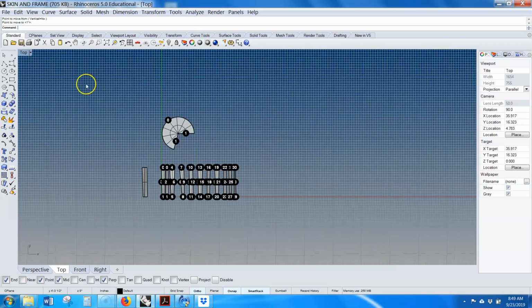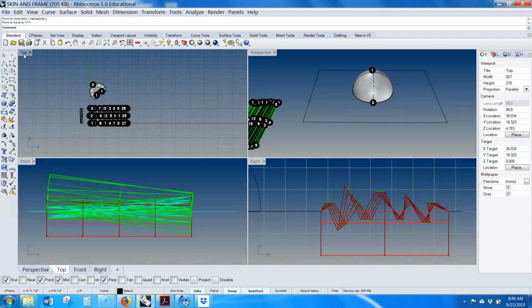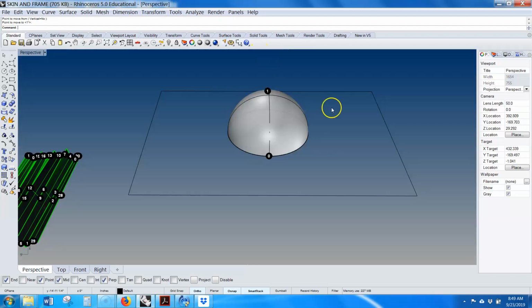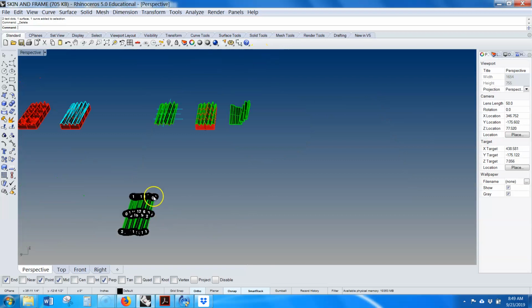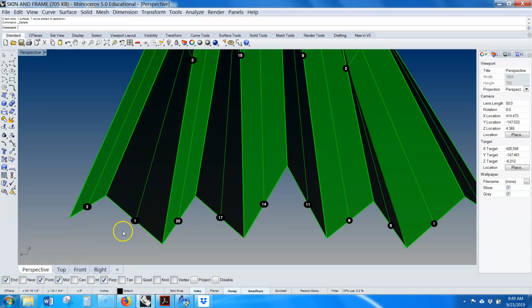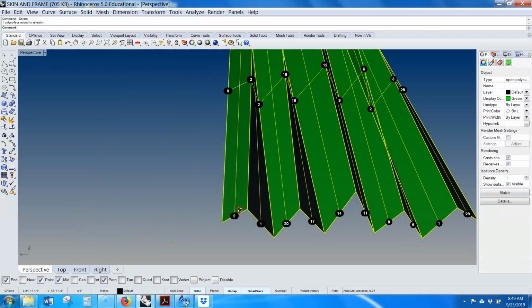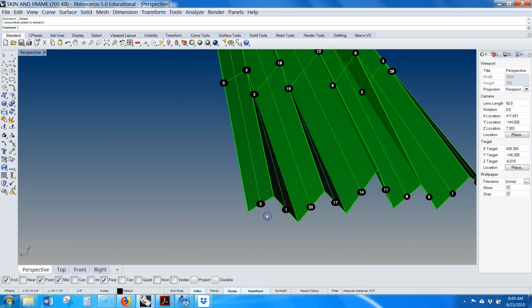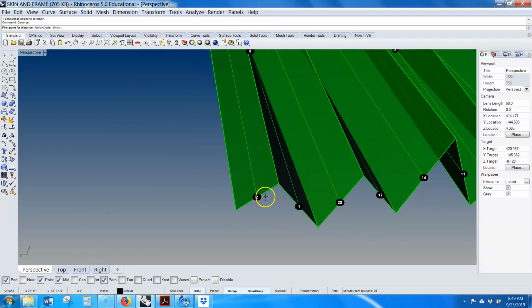Okay, so does everyone basically have an overview of how to do these things? Try to 3D rotate things flat. Then you know they're flat. You can use the unroll command for twisted surfaces, but just verify the edge length. And just to show one more time what we mean by that, be sure you're doing this, everyone. If I unrolled this, everybody look up here, I want to come over here and measure by typing distance.